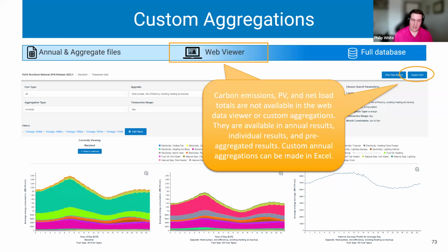And one last caveat, we generally discourage using time series aggregations made with TMY3 weather files. TMY3 weather is not aligned across weather station locations. So DC could be having the hottest day on record, while Baltimore, an hour away or so, depending on traffic, has an unreasonable cold snap. Using TMY3 time series results within a weather file location is fine, or aggregating annual results, but just be wary of aggregating time series.